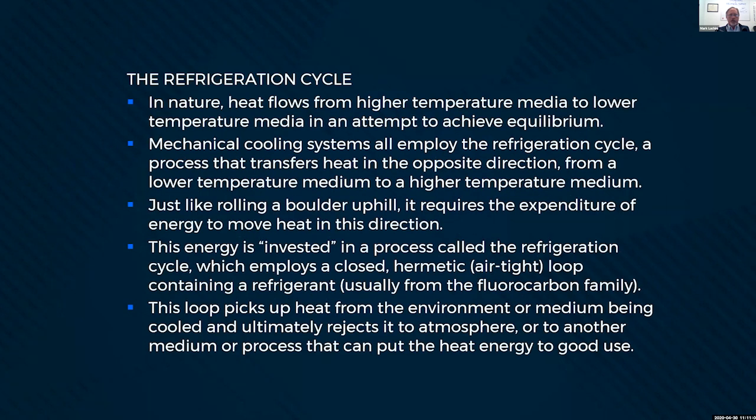So this loop basically picks up heat from the environment or whatever medium is being cooled, chilled water, for example, and ultimately rejects it to atmosphere. Or if there's another process that can use that waste heat, we'd basically insert it into that process. One form of energy recovery.